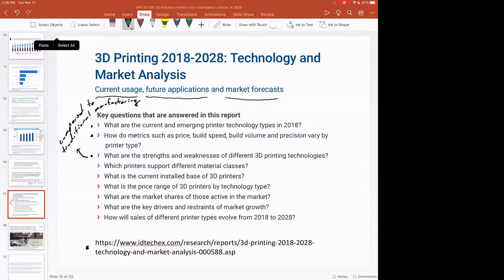And we haven't talked too much about the weaknesses of additive processes. But if we're doing material extrusion AM, of course, you probably have to post-finish it because you don't have a lot of consumer goods with the road extrusion pattern in them. Or if you're going to do SLA, how are you going to post-finish those? What post-processes are needed? How much curing is needed? What's the resulting strength of the parts? All those things matter as strengths and weaknesses in AM.